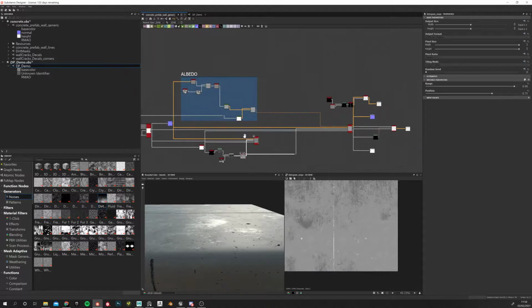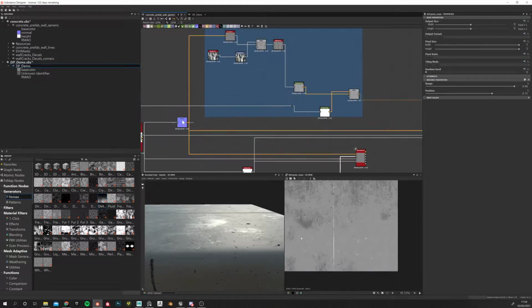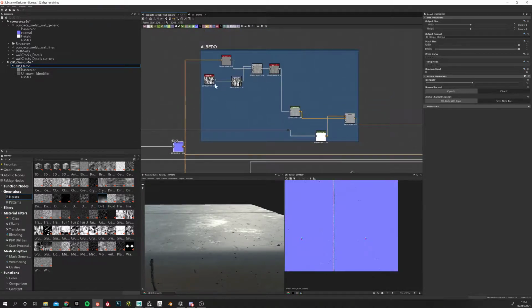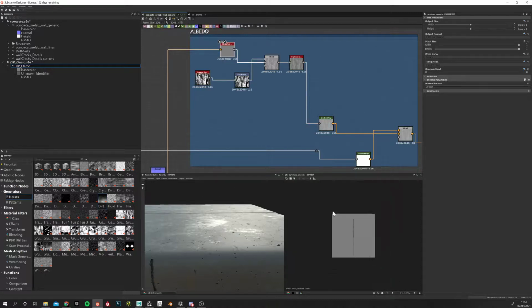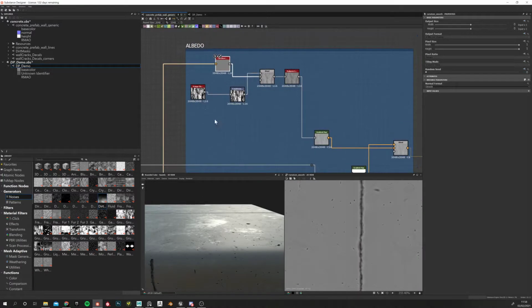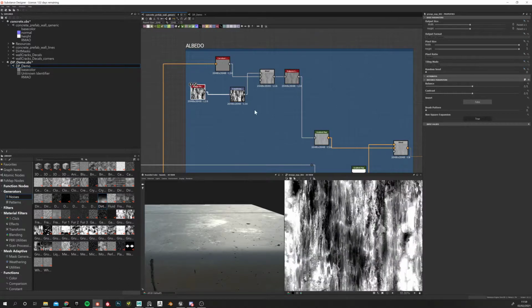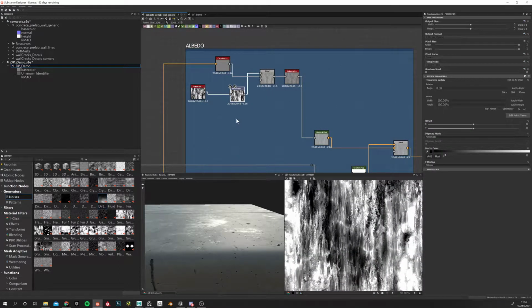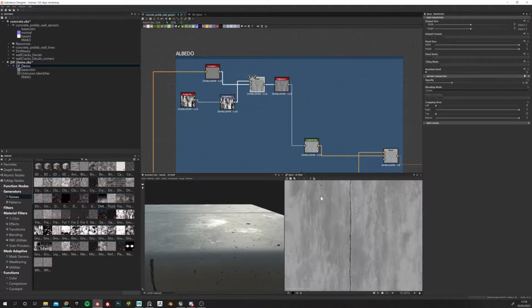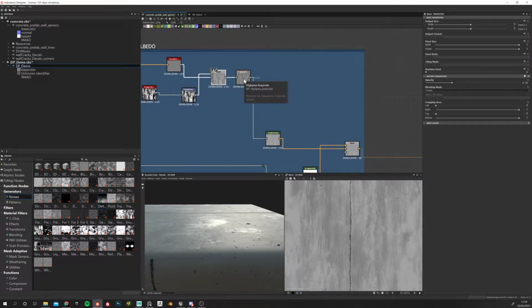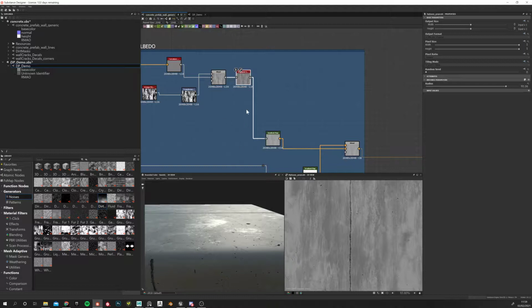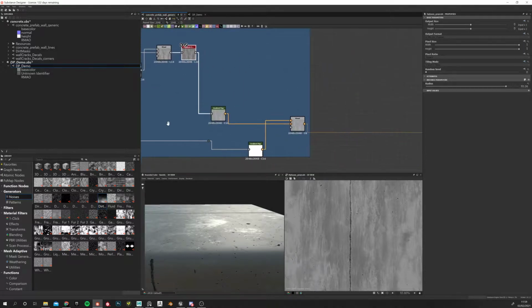So once I have that, from the actual normal, I can derive my color. And you do it by putting a node called curvature smooth, which takes the normal map and creates a grayscale version of it. Then I took this grunge and made it smaller with a transform 2D, I believe. Then I blend it with this. You can see that I blend this grayscale with this, just based on the observation of the material. Then I applied a high pass grayscale just to make it a little bit more even. This is another node you should explore.